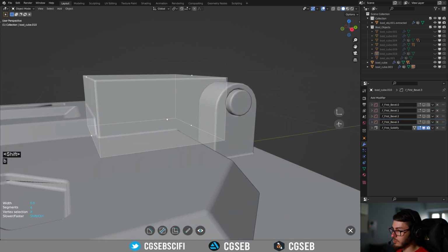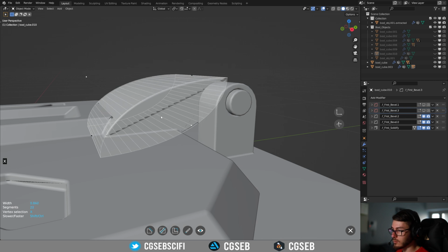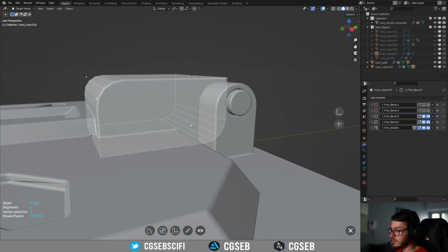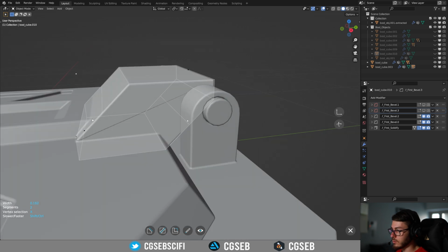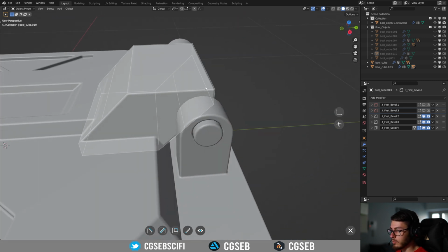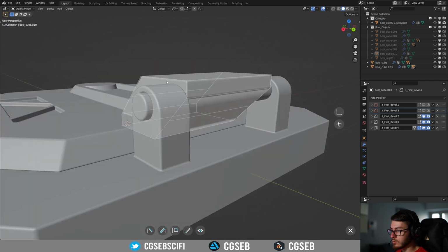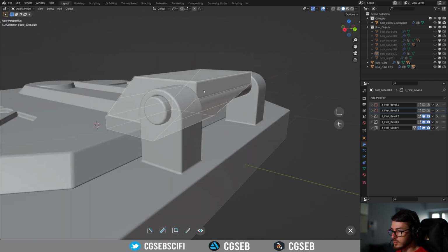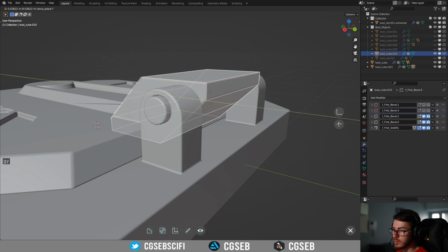So press B for bevel, X to deselect all the corners, and then select this one, and we're going to select also this one. So this time we want to make it straight, so press C, and then like this. So you need to just find the middle point where you are happy with it. So I think this is good. We're gonna make it a little bit here, so we can just press G and Y to move it like this.